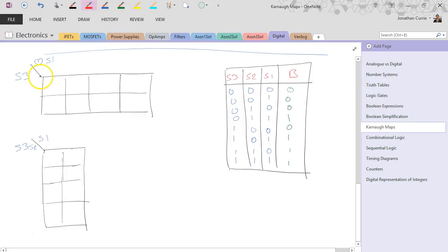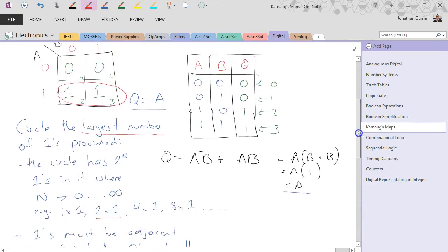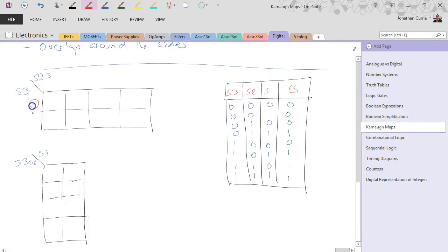On the outside, we're going to put in numbers again. So in this case, 0, 1. But note carefully what happens when we've got 2 inputs on one side. 0, 0, 0, 1, 1, 1, 1, 0. Now, be very careful in noticing what I did here. Note that this is not counting in binary. The way K-maps work is that between each row or column, only one input can change.